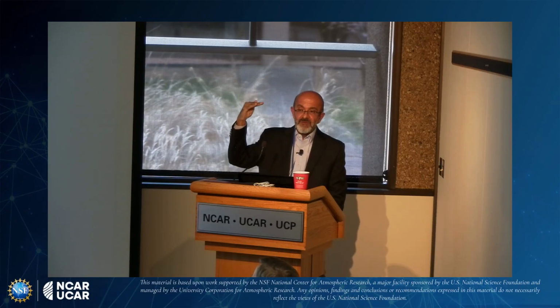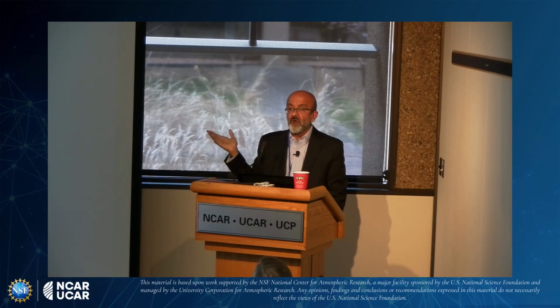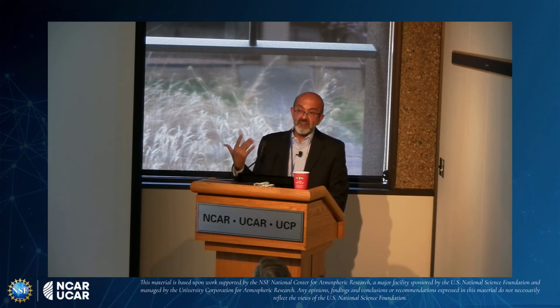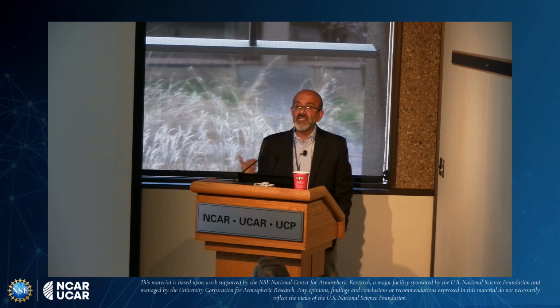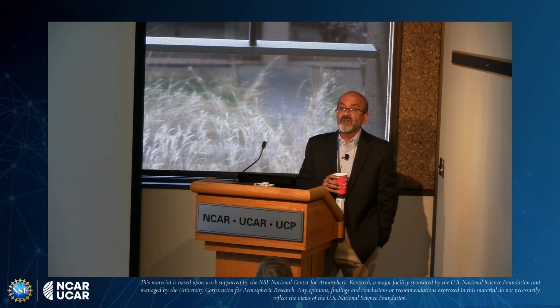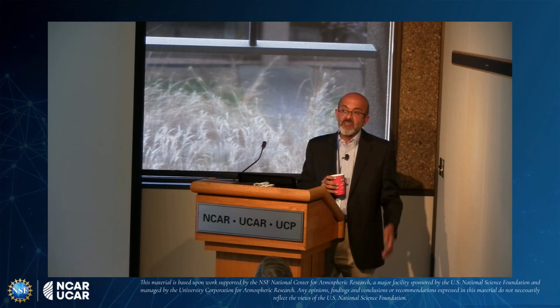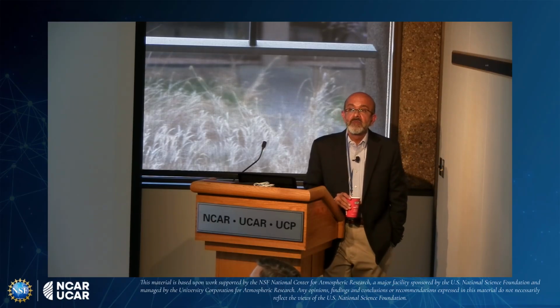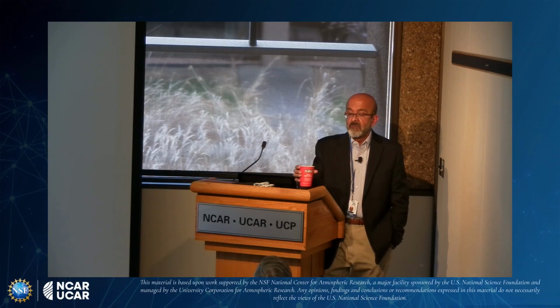The number of layers you can have, the way we've done it, is up to 5. We've done 3. 3 is more than what we need. I mean, 3 is just right. I wouldn't need 4 or 5 unless you have a very wiring-dense design, but you can easily go up to 5. The vendor I'm talking to from ASU can do 5 layers. It's kind of like a 5-layer PCB. Yes. What are the typical assembly costs for, say, a 1 centimeter by 1 centimeter?